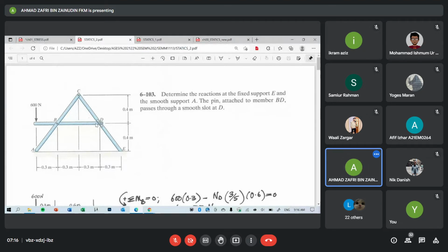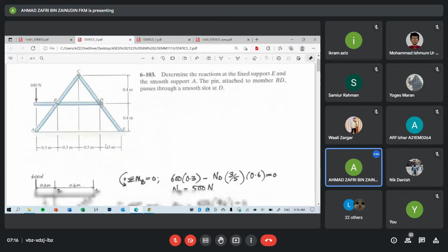ABC also is not under axial load. So to determine the strength of this structure, or the size of every member here, we will do it later with transverse load. For this structure, we cannot use P over A. Let's look at the next one.